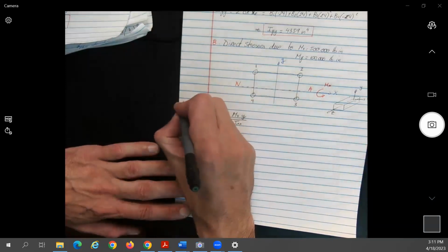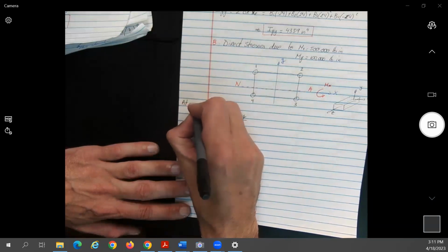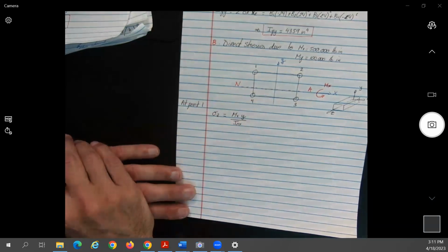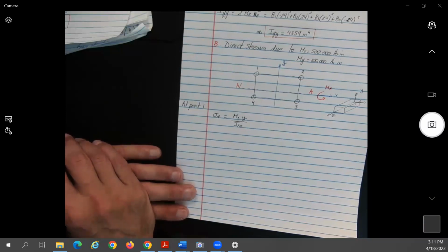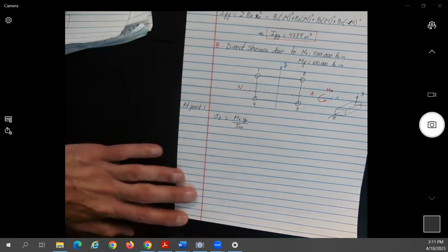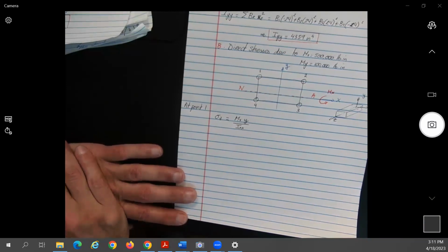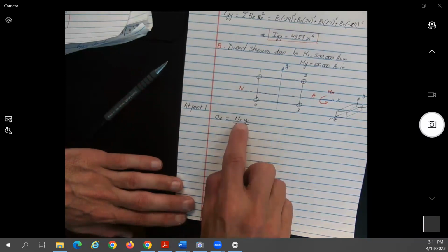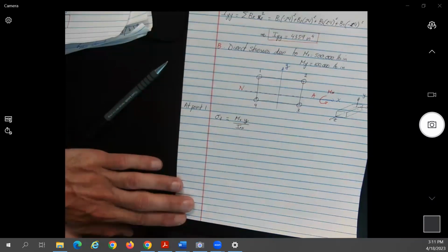Okay. So yeah, the thing is that we need to specify which point. So let's say make all those calculations at point 1. Okay. I was just curious. So we're doing the moment Mx first, and then you go to My? Yes, and then we combine them. Correct. And the reason we can do that is because we assume that every deformation is linear. So you can use the principle of superposition if you want to think about mathematics. Correct. But even if you have the whole equation, even if you have all the terms, you can just put the Ix up, but just assume the other one to be equal to 0. Okay, that should not affect the sign.